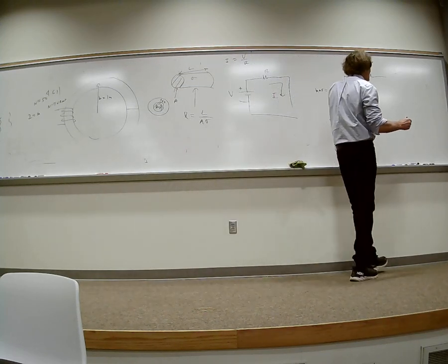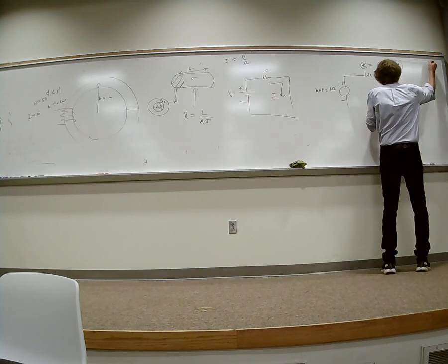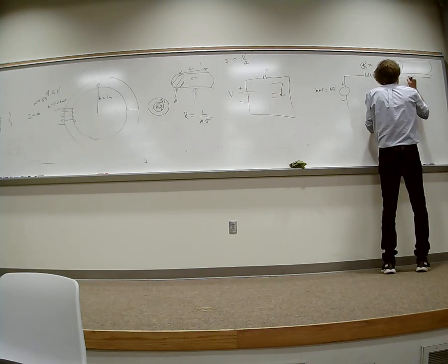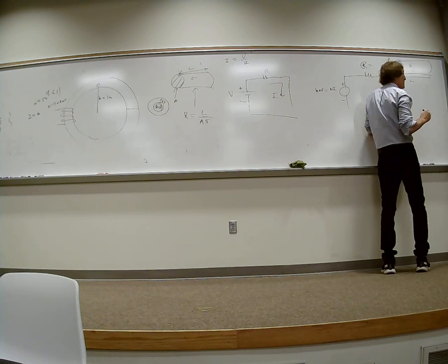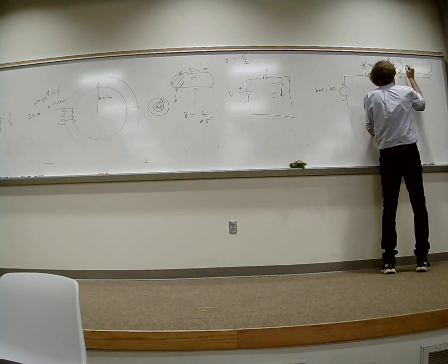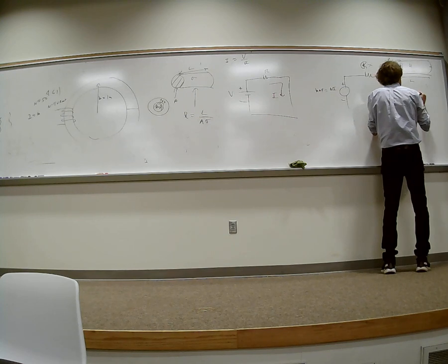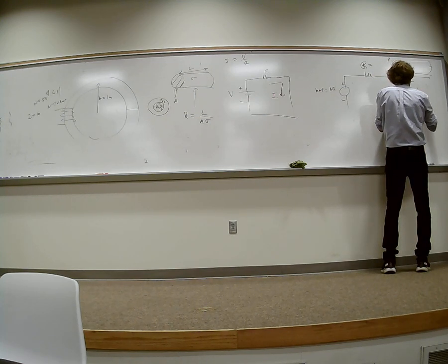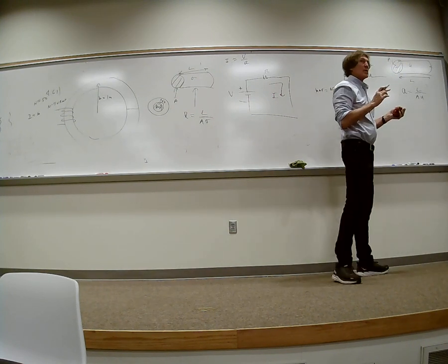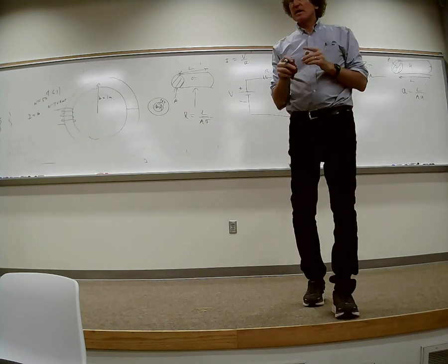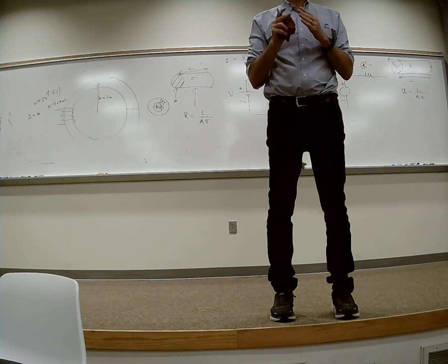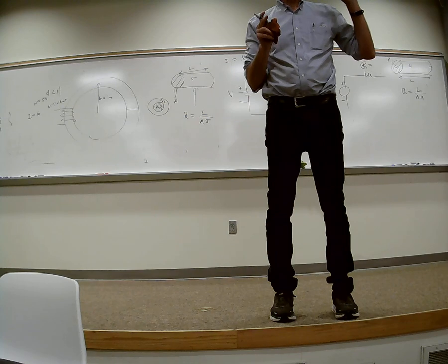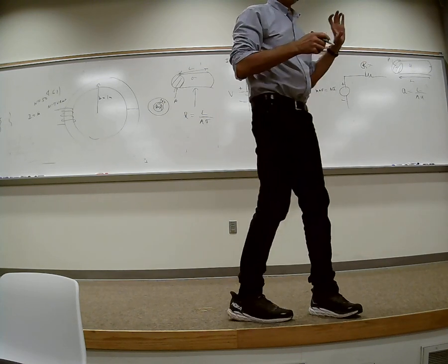So over here, if you have a magnetic material with a given length L, a cross-sectional area A, and a permeability mu, the reluctance between here and here is proportional to L, inversely proportional to A, and inversely proportional to mu. Now mu is mu relative times mu naught. One thing I'm going to say about magnetic reluctance is that you might think of it as what opposes the actual magnetic field B, or opposes the flux developed. Just go with me on this, you'll see how it works.